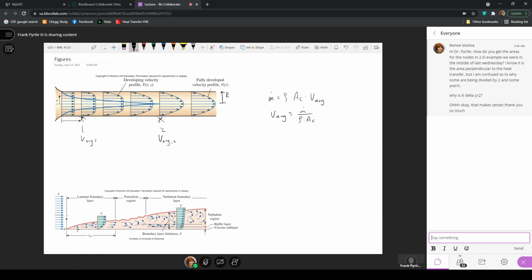Here we have the existence of what's called an inviscid core, this blue line here that grows together from the perimeter or the radius of the pipe towards the center line. This inviscid core is just a place where viscous effects have not yet affected the flow. But once they grow together, this is what we call the hydrodynamically fully developed condition.